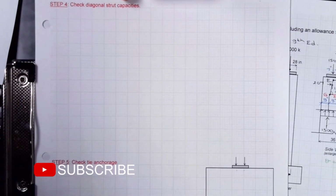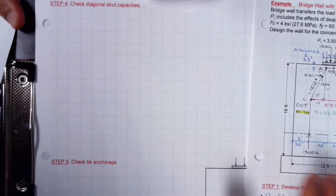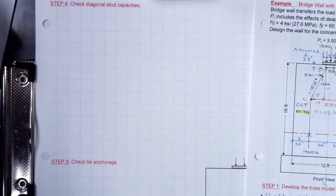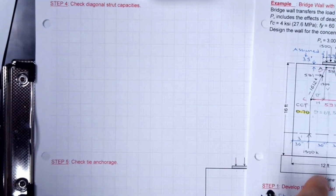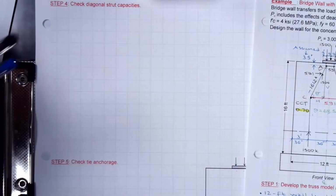Couple more checks. Diagonal strut capacities tend to be critical, so let's look at this. Again, I'm going to be doing this check twice. I need to check strut AC for the original front view model, and then for the through thickness model I'm going to check strut EG.